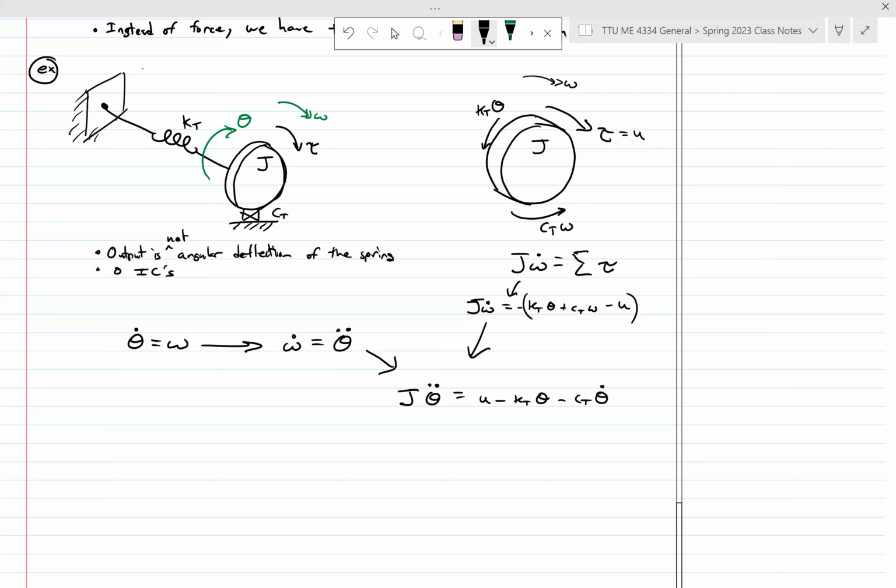The spring and the damper, as long as they make physical sense, want to stop that motion, right? Whatever the positive omega direction is, or the positive theta direction for the spring, they want to stop that. They want to return back to their equilibrium, to their rest. Spring wants to go back to its original position, doesn't want to have any potential energy in it. A damper doesn't want any movement whatsoever, okay?